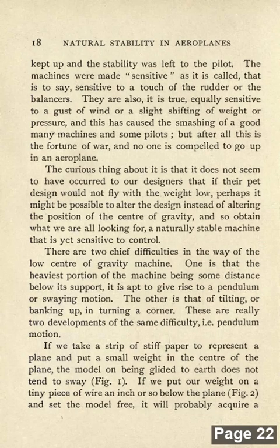The curious thing about it is that it does not seem to have occurred to our designers that, if their pet design would not fly with weight low, perhaps it might be possible to alter the design instead of altering the position of the center of gravity, and so obtain what we're looking for, a naturally stable machine that is yet sensitive to control. There are two chief difficulties in the way of a low center of gravity machine.